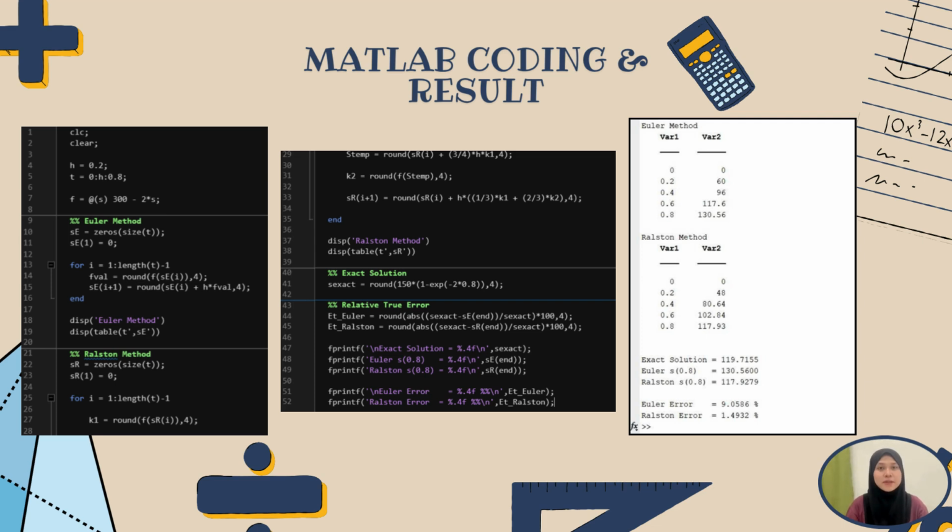Next, for the MATLAB coding part, a program was developed to automate the calculation for both the Euler method and the Heun method. First, the differential equation, initial condition, step size, and time interval were defined in the code. MATLAB then performed the numerical calculation step by step using the formulas for each method. The exact solution was also included in the program so that the numerical result could be compared directly with the actual values. The output was displayed in a table showing the estimated motor speed and the corresponding error for each method.